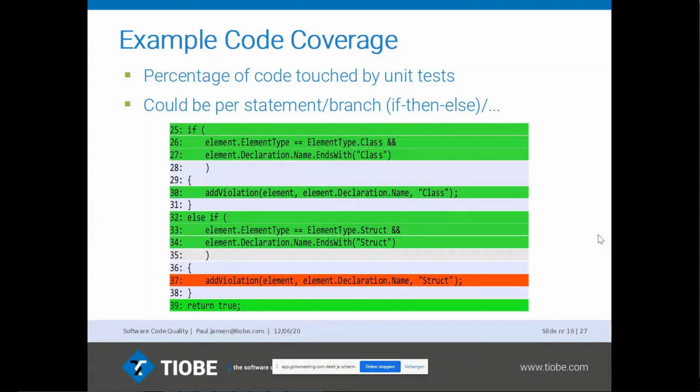We take the average of all code coverage types. The only one we exclude is function coverage, because function coverage is about, suppose you run a test, is this function touched or not by this test? So that's a bit easy. It's only seeing whether a function has been called, and that's not sufficient. So we would like to look at statement coverage, what statements are actually covered, and branch coverage, etc. And we take the average of that.